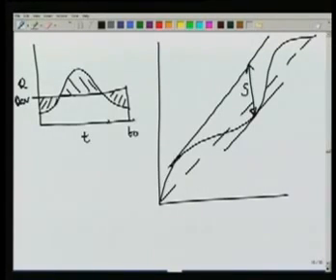These lines are drawn at the ridge and the valley, so the highest portion and the lowest portion of the mass curve, which is the volume versus time. The difference will be the required storage.